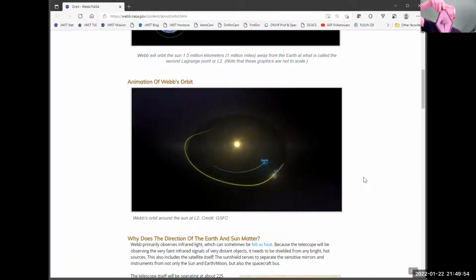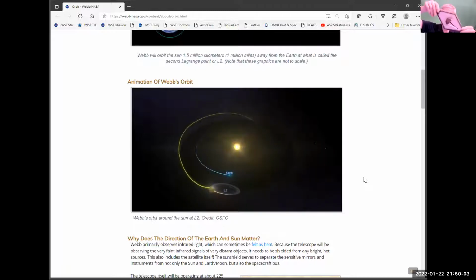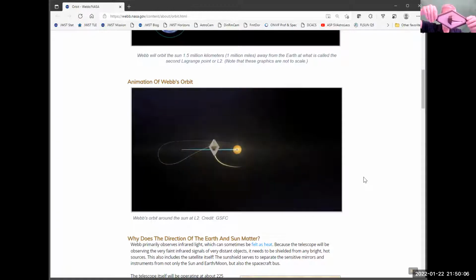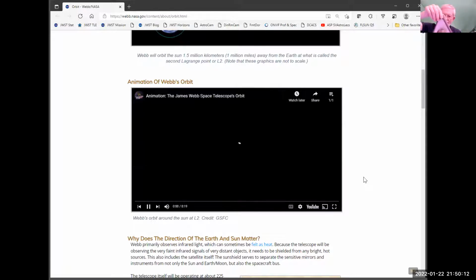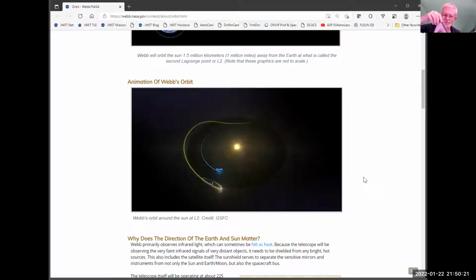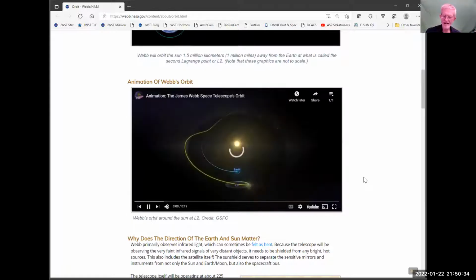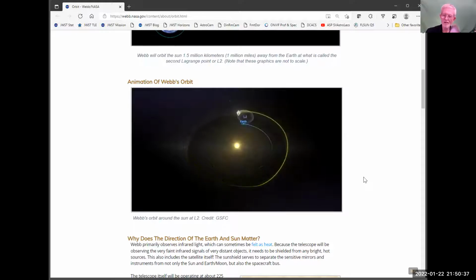And what you'll do is you'll spin it a little bit, and then you'll let it spin down, and then you'll fire the latitude thruster to rotate it like this. And now your wheels are available for full rotation again, and then you'll finish the rotation up. So depending upon what you're observing, you may need to use the momentum wheels and the rockets, because the momentum wheels have a top speed. And once you're pushing against the inertia of the spacecraft with the momentum wheel, when it reaches top RPM, you're not going to go any further. It's just going to sit there. That's the Achilles heel of momentum wheels, that and their bearings wearing out.